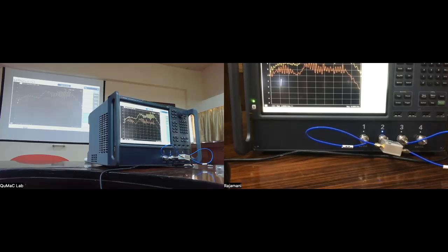So remember that it's not that the phase itself is changing of one of the signals. What is happening at any port is that multiple signals could be combining with a certain phase relationship, and that phase relationship could change with frequency, which could give rise to the output signal both having an oscillation in magnitude and also in phase, right? It's like basically saying if I combine two sine waves with different amplitude and phases, the output will not only have oscillations in amplitude. It can have oscillations in phase as well. So again, these are very small variations.